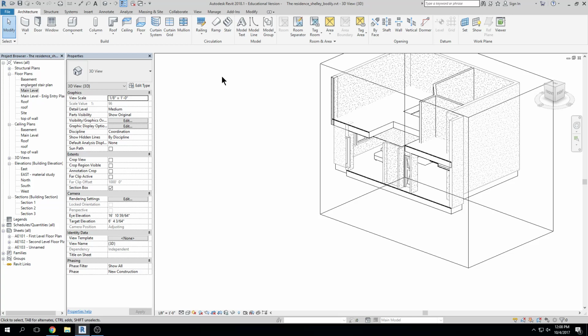One quick question: if you're going to do a drop ceiling in a closet, you don't really need all the walls around the closet, you just need a 2x4 to hold the ceiling. Do you still have to draw walls for the soffit wall coming down? No, you don't. How do you show the wood around to support it? You're not going to worry about that. So the walls themselves would just support the structure for the drop ceiling, right? And then you'd show the ceiling with gypsum board and a stud. Okay, that makes sense. Thank you.